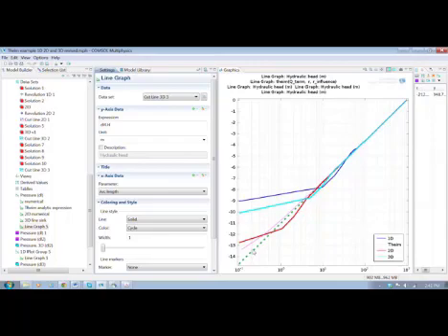One of the big things that we can do to change this error here is experiment around with the grid. If we make the grid finer, then this erratic behavior, you can see there's a point right there. This is probably one point in the finite element mesh, and this is another one. So it's this coarseness that gives us this kind of error. And when we put the well in as a 0.1 diameter hole, then it made the mesh around that smaller, and that's why this one is behaving more accurately.